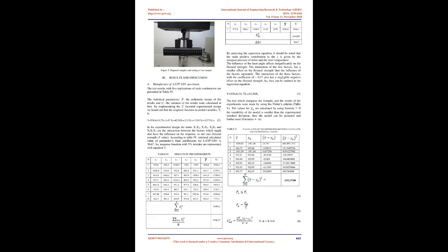The experimental design was made on the LATP processes for obtaining laminate panels from UD1 and UD2 thermoplastic prepreg materials, and the sample designations are LATP UD1 for laminate based on UD1 and LATP UD2 based on UD2. The determination of the factor levels and coding of the variables is conducted in accordance with Table I, respectively for the type of materials. Namely, for the first factor, sample LATP UD1, the low and high levels are set at 360 °C and 380 °C, respectively, for the second factor at 270 N and 370 N, respectively, and for the third factor at 22° and 25°.